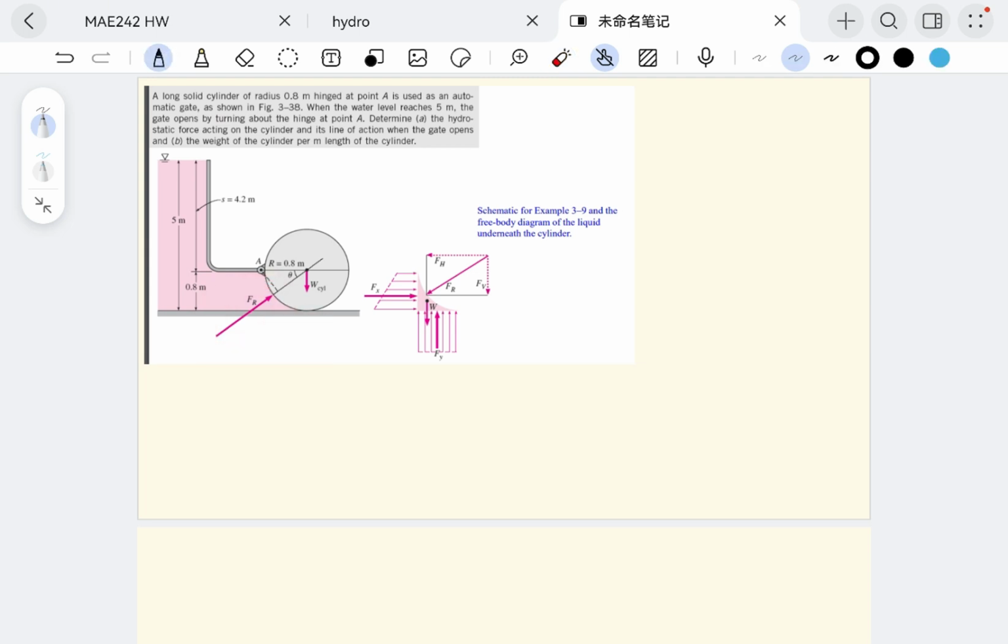From the force pressure area equation, we know that pressure is equal to force divided by the area that it is acting on. So the pressure and force is acting on the area and it's perpendicular to it. So we got F is equal to PA. But now we have a new unknown, which is P. How do we find P in the water?